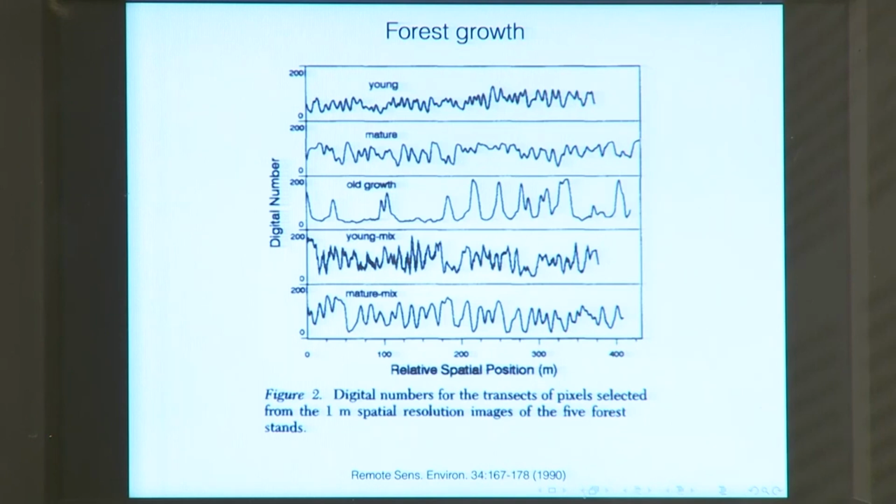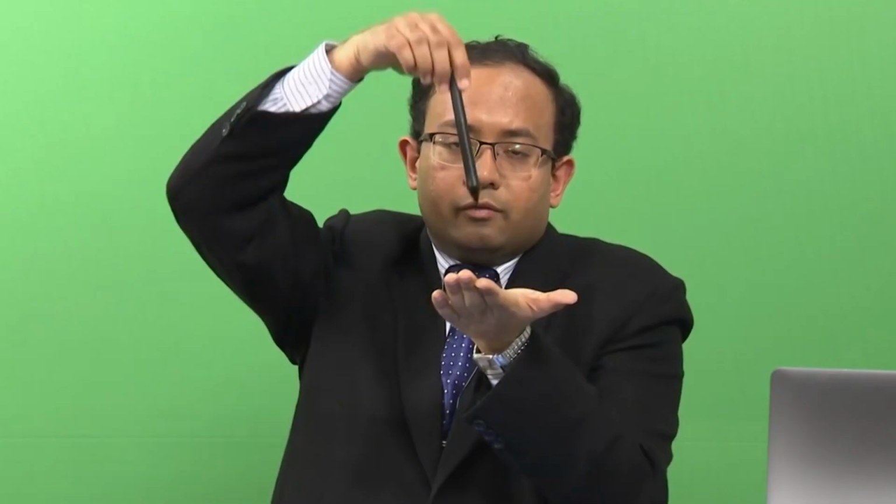So, in this lecture we started by looking at what a LiDAR is. LiDAR is light detection and ranging. It is a system in which you are using a laser beam to scan the surface, and because the laser beam requires energy to operate, this is an active remote sensing system. So, you have a laser beam on an aircraft and this is scanning the surface, and when the laser beam goes down and interacts with the surface, there is a reflection, and the reflection is measured on the aircraft.